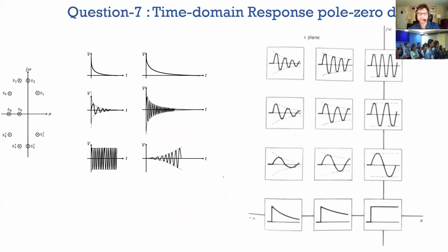Okay, this question was really to give you a feel for what a pole-zero location does, so I don't want to go much into it. I'll just show it pictorially. In a system, if you have poles on the real axis, that's over here, then your responses are always asymptotic. In other words, they look like an RC time constant. So there's no ringing, there is no fundamental frequency component to it.